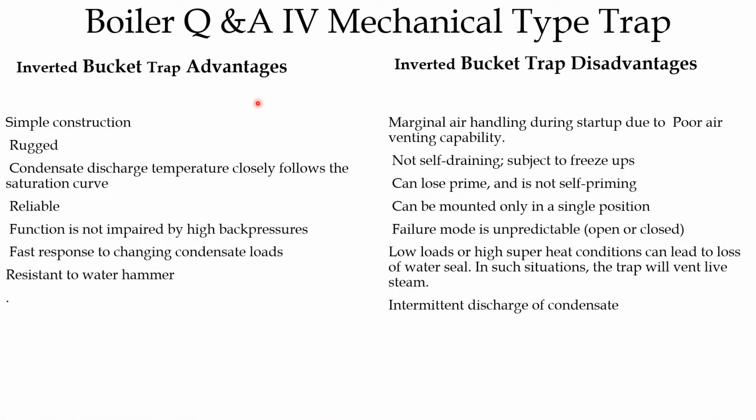Now we can see the advantages and disadvantages of the inverted bucket type steam trap. Advantages are it is simple in construction and rugged, so it is resistant to water hammer. Condensate discharge temperature closely follows the saturation curve. It is reliable. Its function is not impaired by high back pressure. Fast response to changing condensate load. So it will work on different condensate loads.